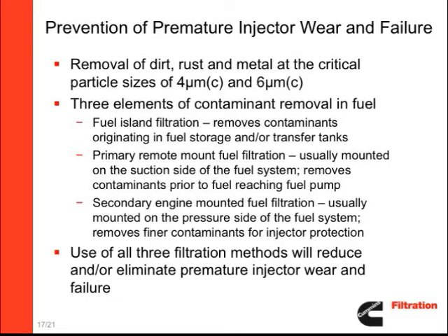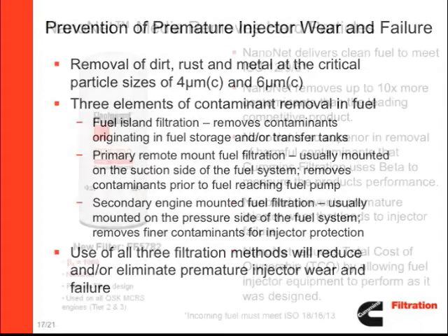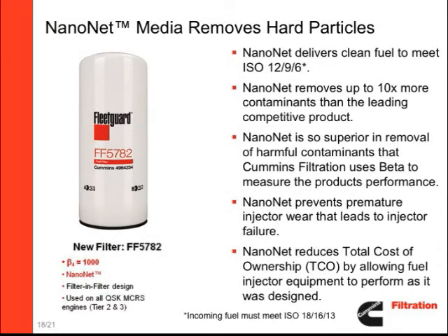Finally, there is the secondary engine-mounted fuel filtration. The system is usually mounted on the pressure side of the fuel system and removes finer contaminants to further protect the injector system. Using all 3 filtration methods is the best way to reduce or eliminate premature injector wear and failure. Now, let's discuss the specific products Cummins Filtration provides to protect sensitive FIE systems.